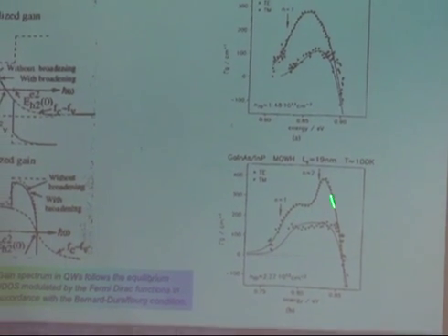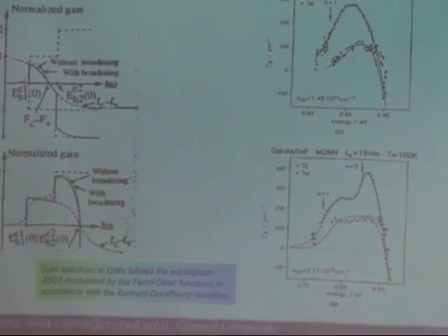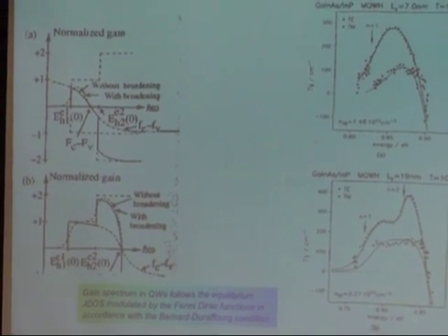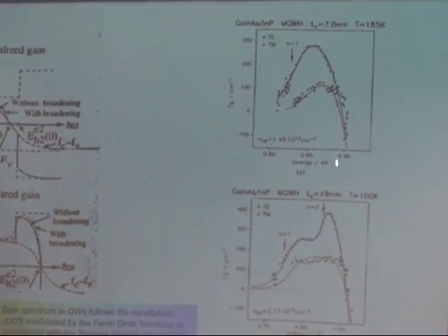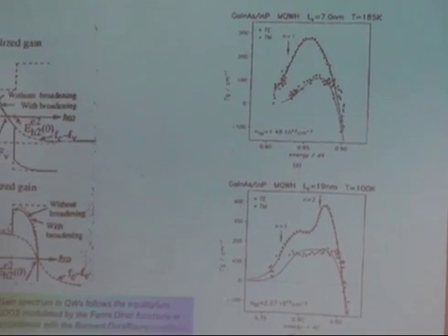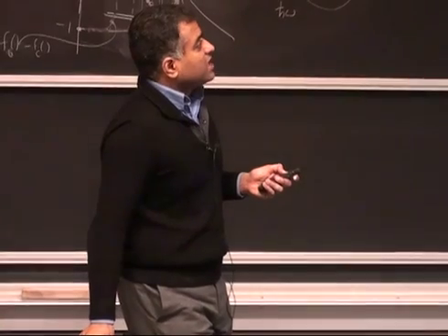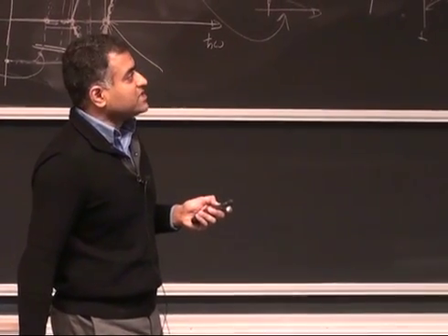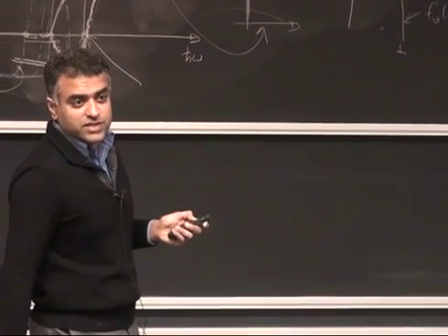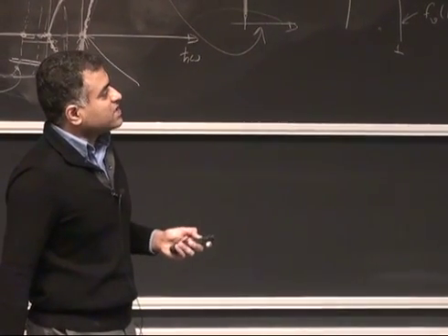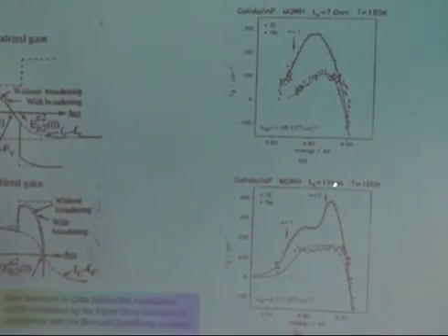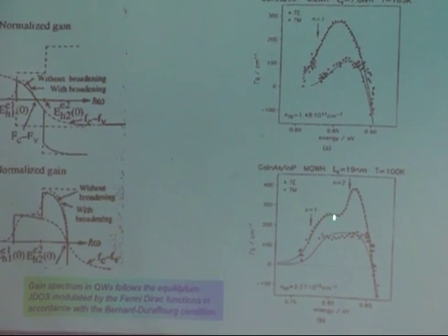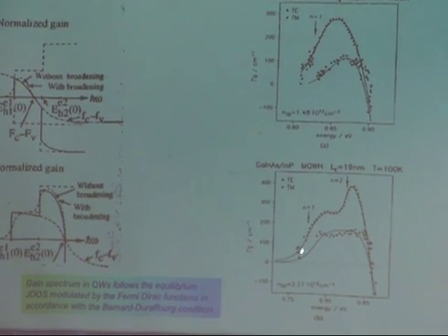It's going to have maybe some steps like this, because you have a DOS that's going like that, right? The solid lines are calculated, and the dots are experimentally measured gain spectra for some infrared lasers, indium gallium arsenide quantum well lasers on indium phosphide. Remember, you can lattice match a certain composition of indium gallium arsenide with indium phosphide. These are multi-quantum well heterostructure lasers. The quantum well width is 19 nanometers. These measurements are done at 19 Kelvin. But you see this now, right?